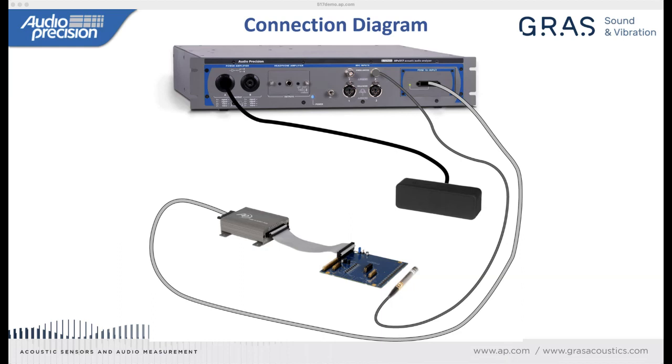For voice applications, we're generally testing up to about 10 kilohertz. And so that gives us just a little bit more physical flexibility in the positioning of everything. But the point is completely acknowledged, and my answer is it depends on the highest frequency that you're interested in accurately measuring. That will determine how mechanically accurate the positioning of all the test articles needs to be.